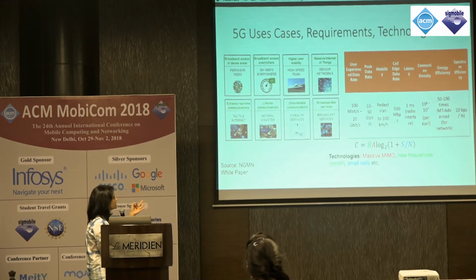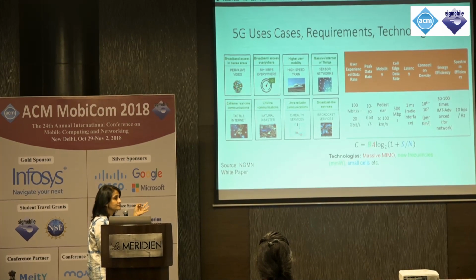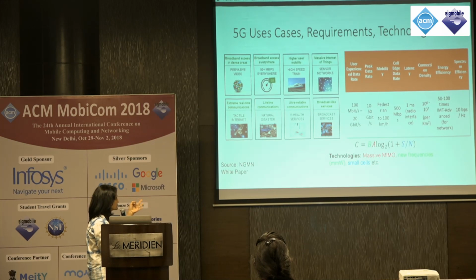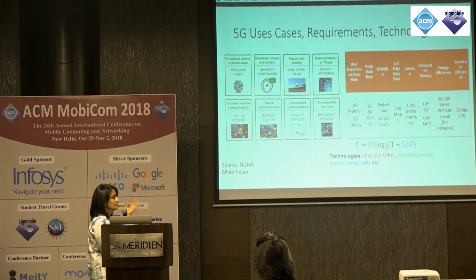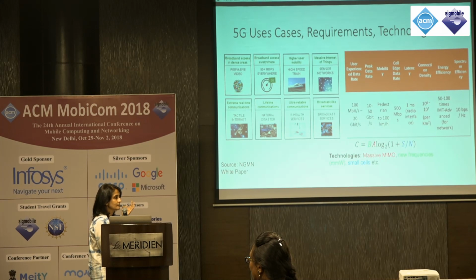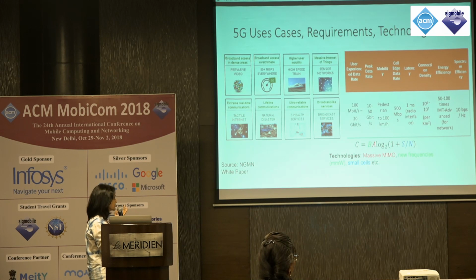And all of these are going to get hit in 5G. So A, which is in red, number of antennas, is what massive MIMO is going to tackle, the degrees of freedom that you can get. B is the bandwidth. We're running out of bandwidth in the low to mid-range frequencies. That is what millimeter wave is going to give us. We're going to get the larger bandwidths in millimeter wave.